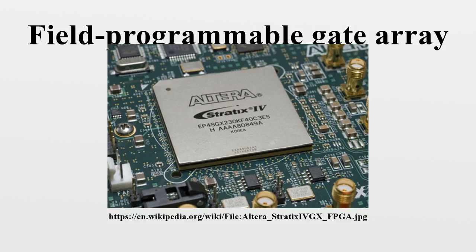Technical design. Contemporary field-programmable gate arrays have large resources of logic gates and RAM blocks to implement complex digital computations. As FPGA designs employ very fast I/Os and bidirectional data buses, it becomes a challenge to verify correct timing of valid data within setup time and hold time. Floor planning enables resource allocation within FPGAs to meet these time constraints.